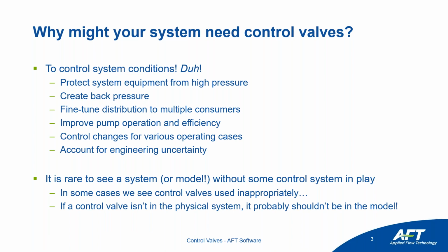So by providing a flow control valve in your model, for example, you are effectively fixing the flow rate at that point. You can add or reduce losses. But if that control valve is not in your physical system, then it's going to be changing your results compared to what should be happening in the physical system.